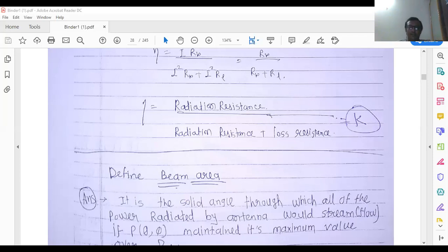Classify the antenna based on the aperture: C, A, B both. Classify the antenna based on the gain: all of the above, high gain, medium gain, low gain. Helical antenna, see this is a helical antenna. What is the impedance of free space? 377 ohm. It is known as a parabolic reflector antenna. Now see all of the parameters affect it: diameter of surface, operational wavelength, antenna efficiency. These factors affect the gain of the parabolic antenna. Answer is C.